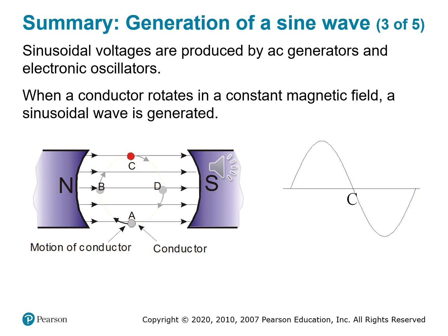On the sine wave, point C corresponds to the zero crossing, where the voltage falls back to zero after reaching its positive peak. This is a turning point in the cycle. The voltage is no longer increasing. The direction of the induced voltage is about to reverse.